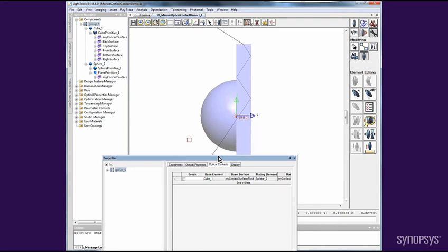Note, one related topic that we did not discuss in this video is when objects are overlapping. In this case, you should set the immersion relationships in the Immersion Manager, as Auto-Declare Contacts is not intended to help with these scenarios.